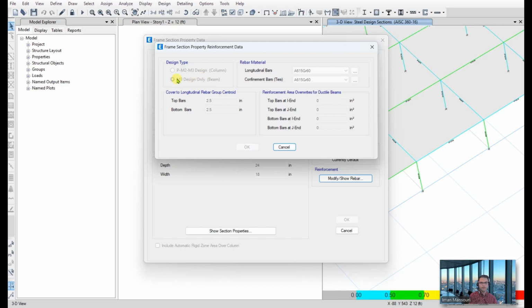So if you have a concrete beam, make sure to unlock the model and then select the first option. That way you can add P or axial load. Otherwise, ETABS won't be able to capture the axial deformations as a result of temperature elongation.